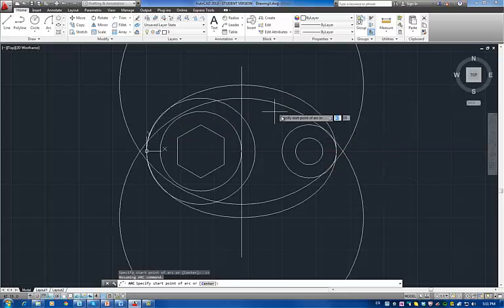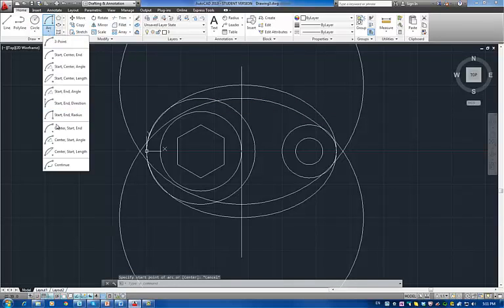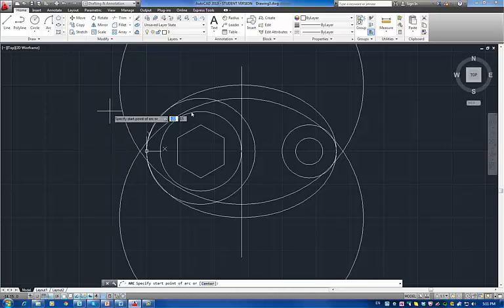And I would like to create an arc from here. I know I already have the circle, but I want to use these intersecting points to create an arc, and then I will delete this circle. So it should be counterclockwise. So this would be my first point, this would be my second point, and then I would say the radius. So again, here I'm using start, end, radius. So I would say here start, end, and then it's asking me for the radius, which is 45. So you see it's overlapping the one which I have.